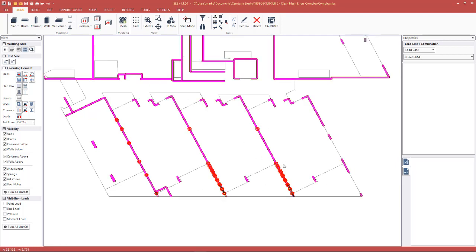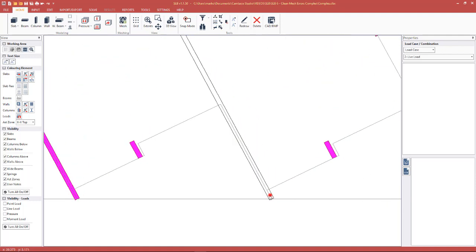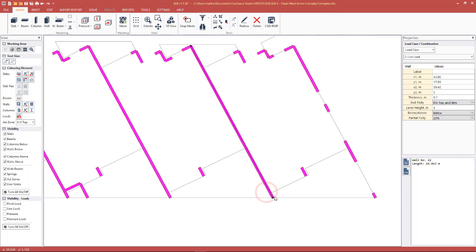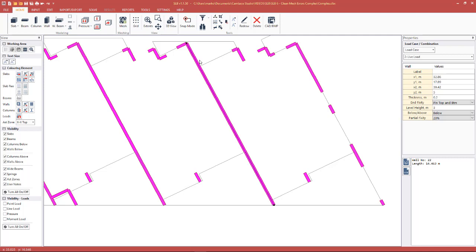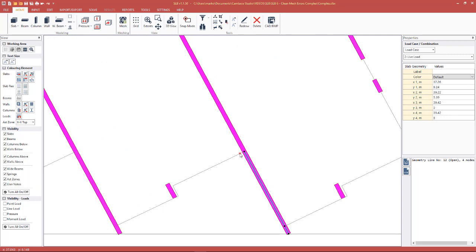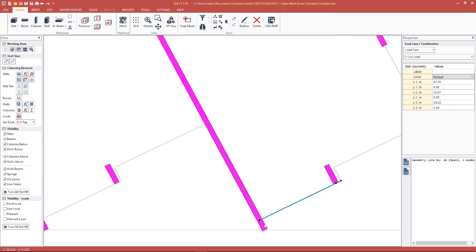Now we'll have a look at these areas. We'll see why the meshing errors were introduced and how we can fix them. So why were the meshing errors introduced? Basically, when we rounded off, we lost some information. So the wall now has one angle, and these geometry lines that are sitting on top of it basically have a separate angle. Now, how will we fix this up? Again, we'll use the extend with mouse and clip tool. Basically unavoidable in this case, and we will clean up these errors.